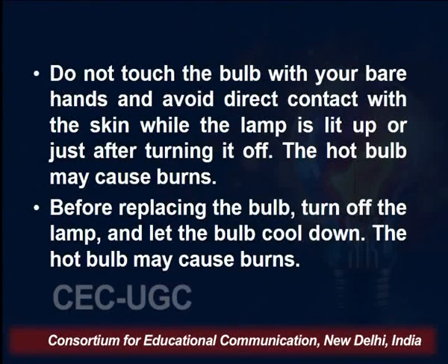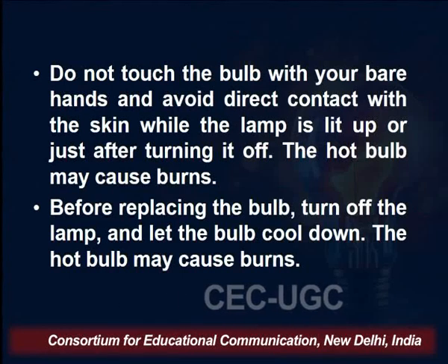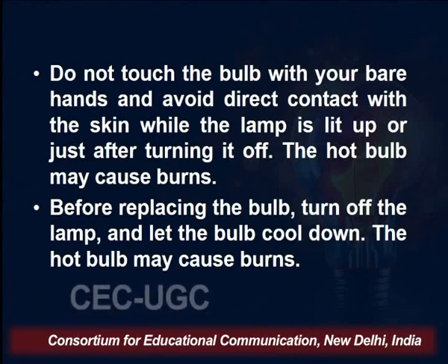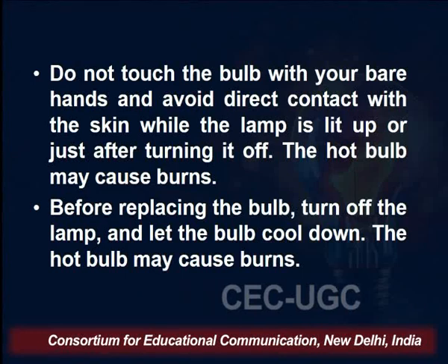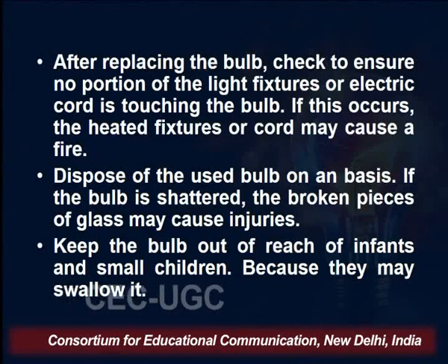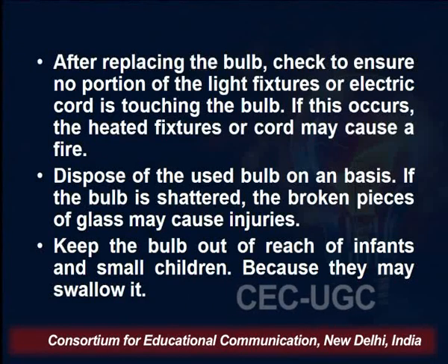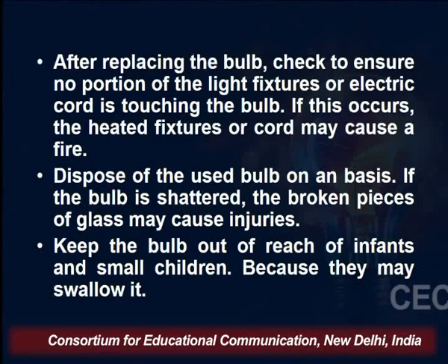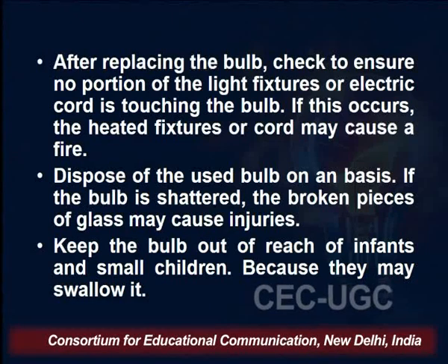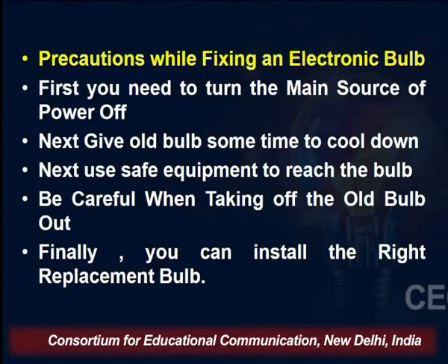We cannot touch the bulb with bare hands, and we should avoid direct contact with the skin while the lamp is lit up and even after turning it off, because the hot bulb may cause burns. So there are many points that we can use for safety. Dispose of the used bulb properly, because if the bulb is shattered, the broken glass may cause injuries. So we keep many things in mind, and we read the precautions.